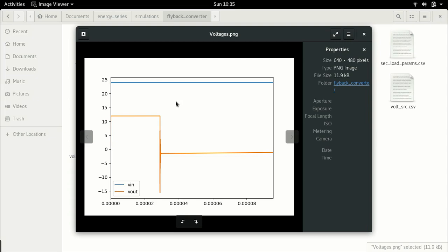Now, in the next lecture, we'll talk about why this is not done. This is not a DC to DC converter. We have to make several changes before we get to a flyback converter. And there are several conceptual problems that we need to solve in order to be able to create a working DC to DC converter with isolation. Because most importantly, we have to deal with the energy stored in the transformer. So with this, I will end this lecture.